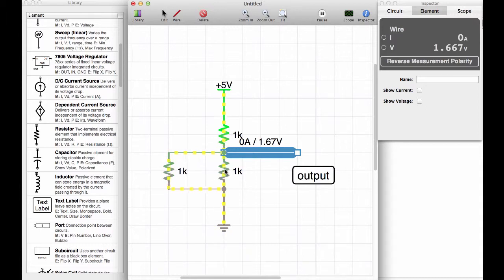So it seems if we put two resistors in parallel, then that lowers the resistance in the lower part of this voltage divider. And that makes sense because you see here now that the current is actually branching into two paths. So we added an additional path for the current down here, and so of course this lowers the resistance in the lower part. What we also see is that all the current that goes in here and the current that goes into these two branches, that needs to be the same, right?